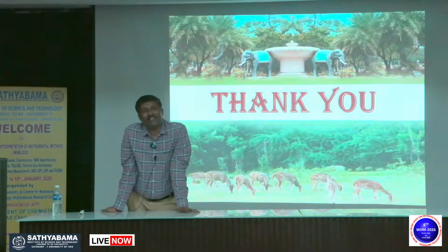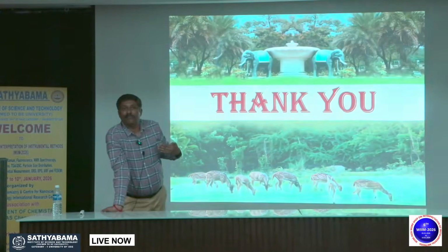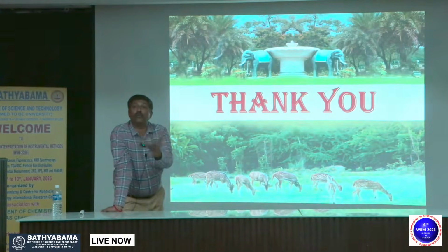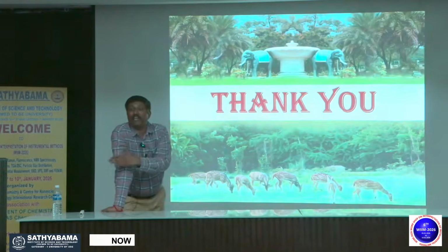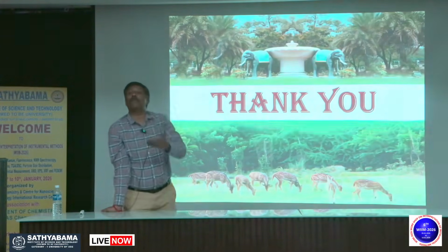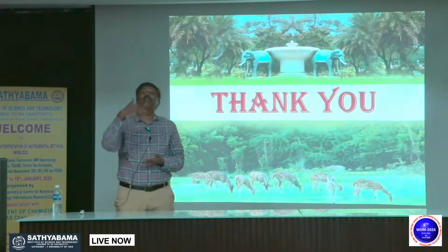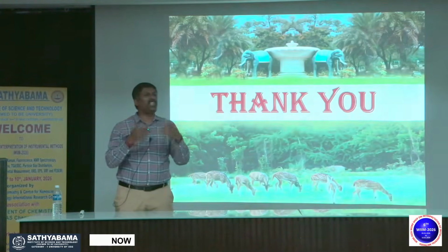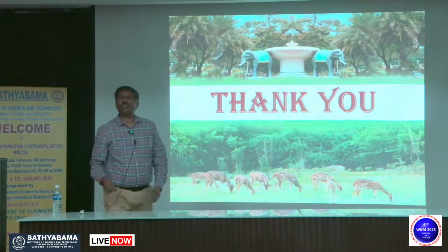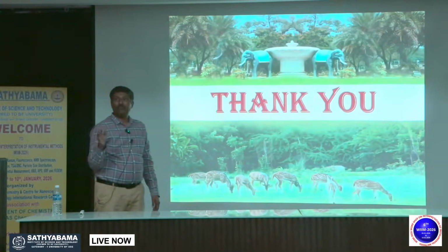Your TD, second sample you again run very fast up to 100 degrees. Let's say your TD is 500. How do you know? Because you ran 20 degrees Celsius per minute and got 500. Because you don't want to lose money and time. The second time also you ramp up to 400 and then you do very slow. This is also another method, but you have to do 2 times. This also will tell you where is the closest answer and what could be the right answer. There are many ways people do. With experience they come up with many things. If your sample TD is 500, why start very slow from 30 degrees Celsius? It is a waste of money, resources. Isn't it?